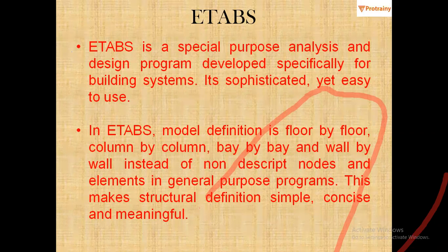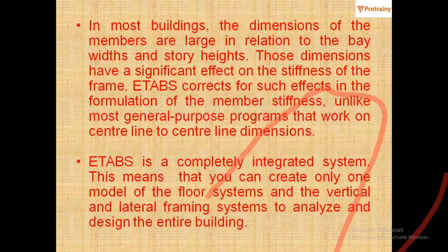This makes structural definition simple, concise, and meaningful. In most buildings, the dimensions of the members are large in relation to the bay width and story heights. Those dimensions have significant effect on the stiffness of the frame. ETABS corrects for such effects in the formulation of member stiffness, unlike most general purpose programs that work on center line to center line dimensions.